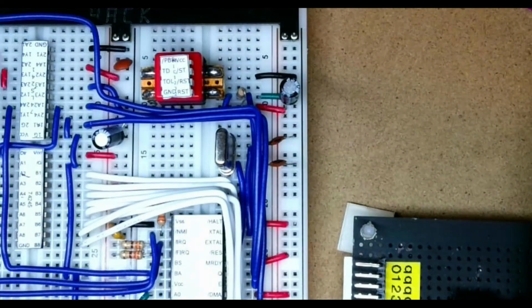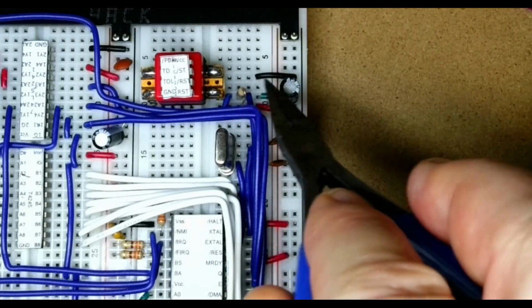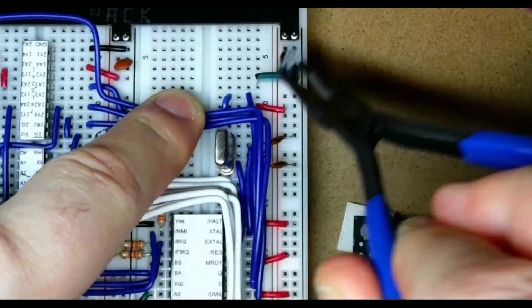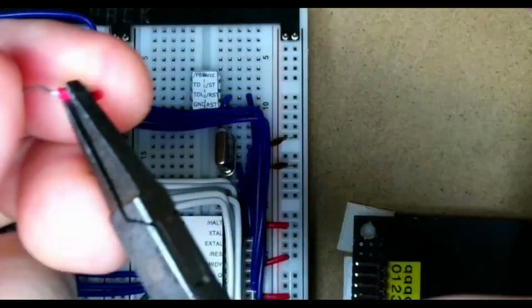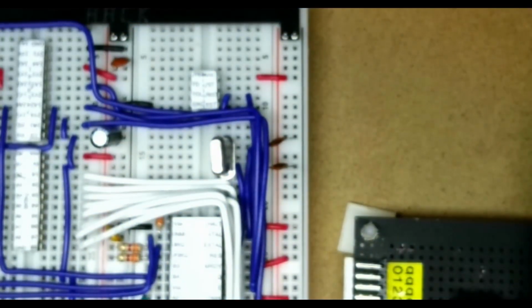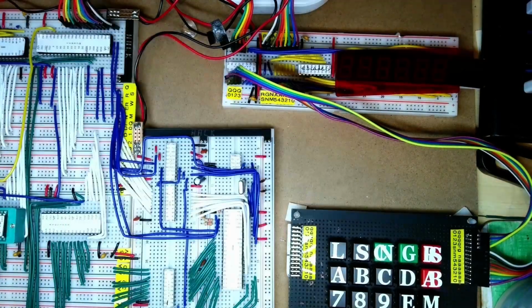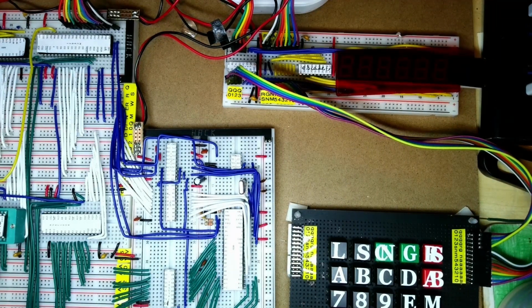You can see there. And if we do this such that the inverted reset actually lines up with this bit here, then in fact we won't have to change too much of the wiring. What we will need to do is obviously wire in the extra pins and things, but it should make things a bit simpler. So just remove the button and the RC combination and the power lines, plug in the chip, put in the plus 5 and the ground lines and the wire also for the tolerance. Now we need to hook in the reset button, so that's coming from the keypad over there. So we've plugged in the reset button input.